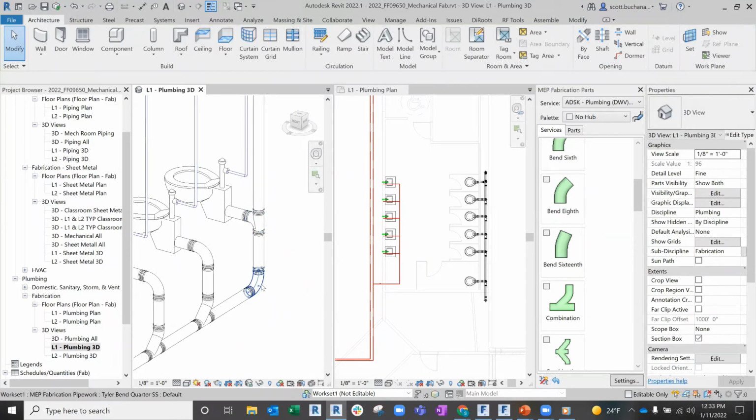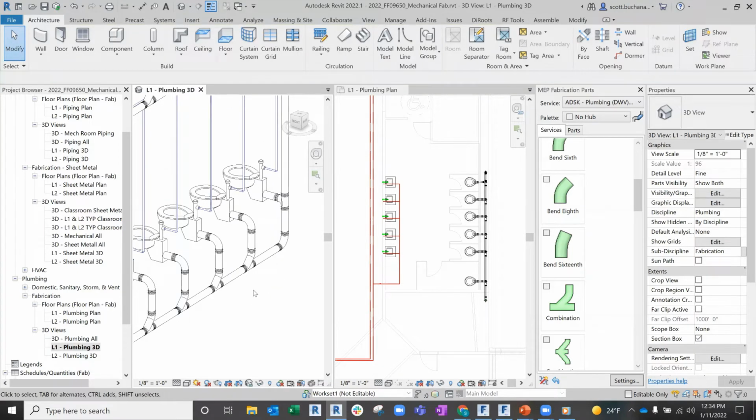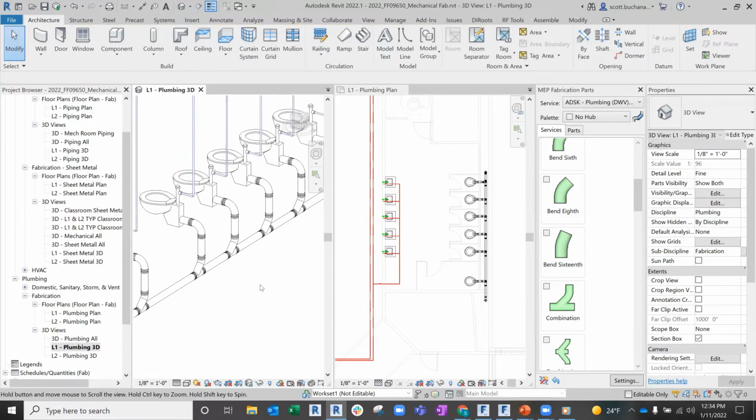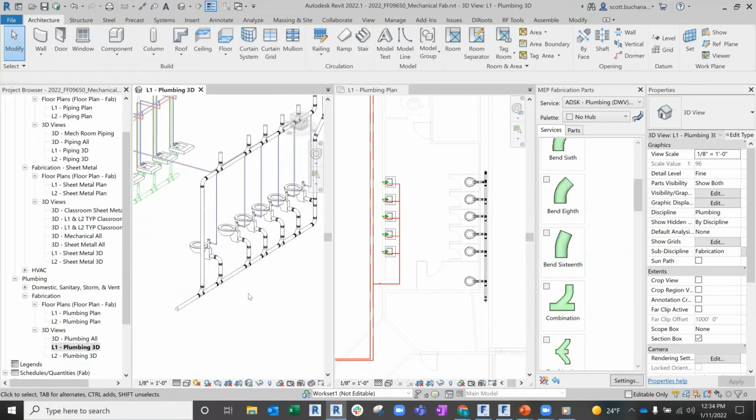Just like if I needed a short radius elbow versus a long radius elbow on the mechanical piping side. So that could all switch out, and that's what we've got. It does keep that direction of flow, and it does keep that connectivity. And if we look on it, there is an 1/8 inch per foot of slope on it. So pretty quick getting that converted.